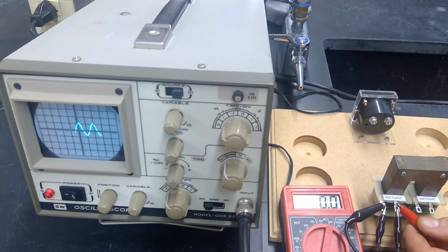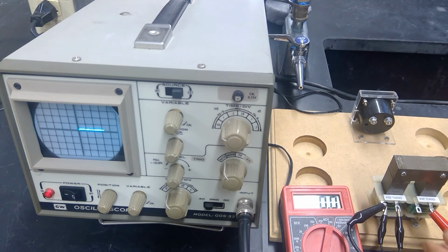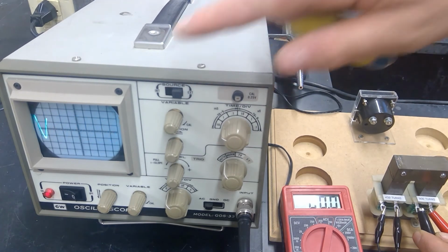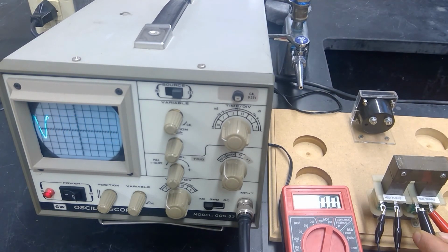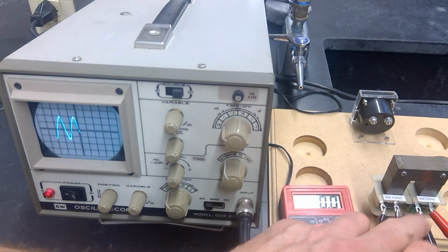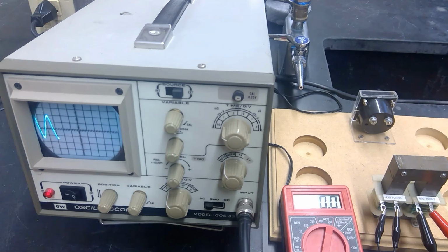And finally, let's take a look at the change in the waveform. And sure enough, it's gotten even bigger. So the waveform increases in the depth or the height, if you want to say, of the wave according to the increase in the voltage. So in conclusion, what transformers can do is step up or step down voltage according to the ratio of wire turns between the primary and the secondary.